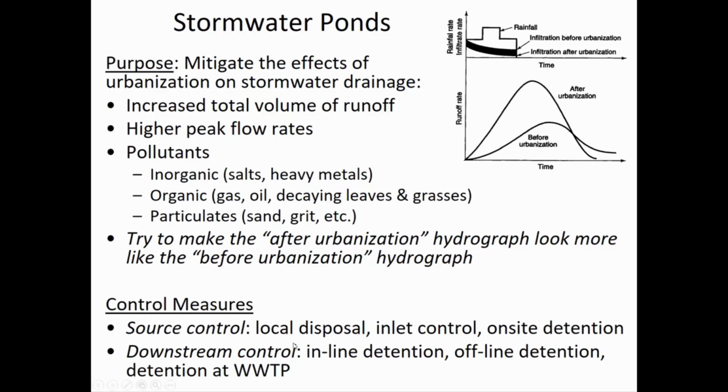So those are illustrations of trying to hold on to the water and delay it as close to the source as possible. Downstream control is talking about measures where the water has already come to a point of concentration, and now you have to build a much larger stormwater detention facility. That big cavern in Japan, the concrete vault that they had, is an illustration of downstream control.